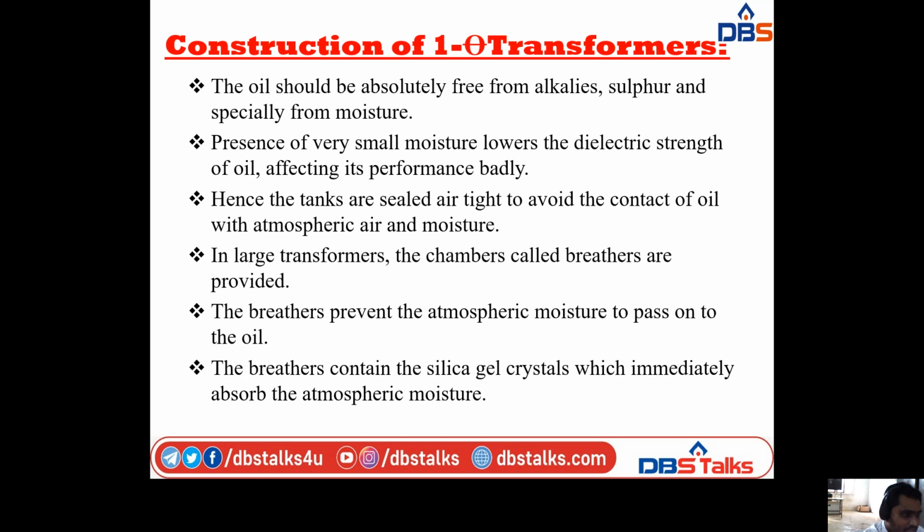The oil should be absolutely free from alkalis, sulfur and especially from moisture. The presence of even very small moisture lowers the dielectric strength of the oil, affecting its performance badly. That's why you have to take care that the oil is absolutely free from these.